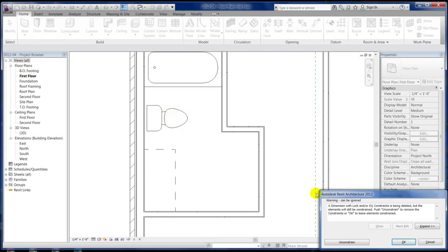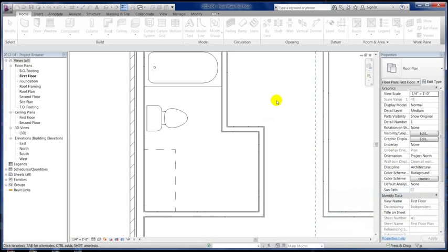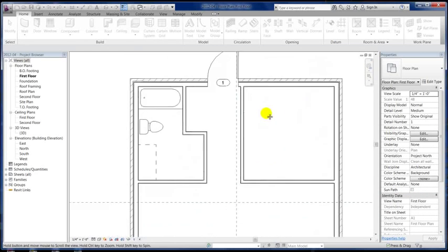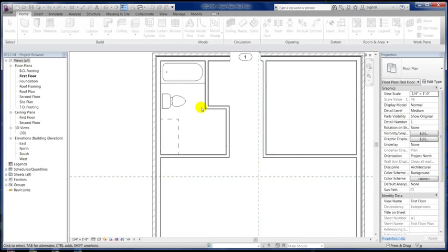And then what I can do is delete that, and since that is a constraint, I can delete the dimension and leave the constraint there to have it always be equal. But I'm just going to unconstrain it. I don't like to constrain my sketches too much or my models too much, because it uses resources and slows down the model. Now something this small, you would never notice it, but it's good habit. Only lock things that need to be locked. Don't go crazy with it.